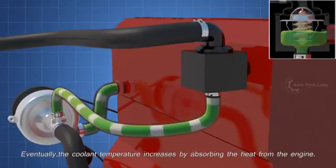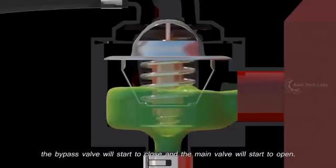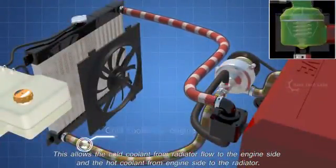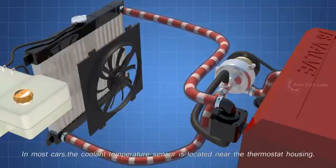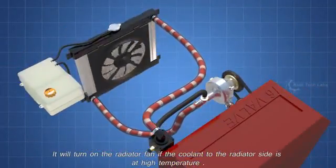Eventually, the coolant temperature increases by absorbing the heat from the engine. Once the coolant reaches a higher temperature, which is usually between 160 to 190 Fahrenheit, the bypass valve will start to close, and the main valve will start to open. This allows the cold coolant from the radiator to flow to the engine side, and the hot coolant from the engine side to flow to the radiator. In most cars, the coolant temperature sensor is located near the thermostat housing. It will turn on the radiator fan if the coolant to the radiator side is at high temperature.